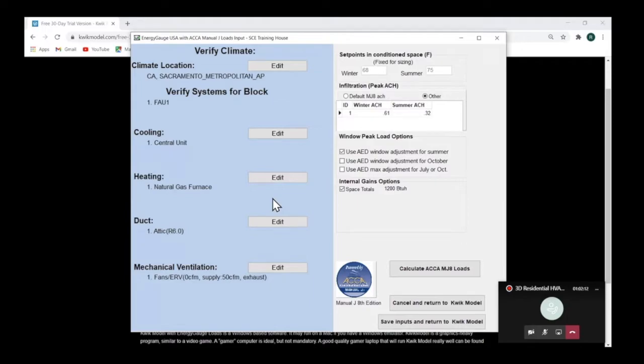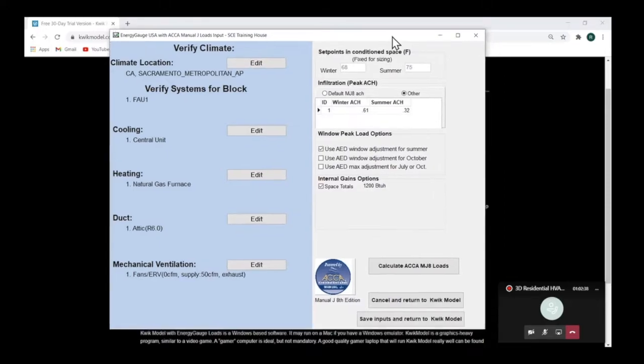You know, what if the house had broken windows? Do you do your load counts assuming a broken window? No, you fix the window. It's the same issue. If the house is really, really leaky, don't design for a really, really leaky house. That house is broken. Fix the house, seal it up, get it down to a reasonable number, and then do your load counts based on that. Okay, so I'll get off my soapbox. That's just my personal feeling about it, and that's how I like to teach it.